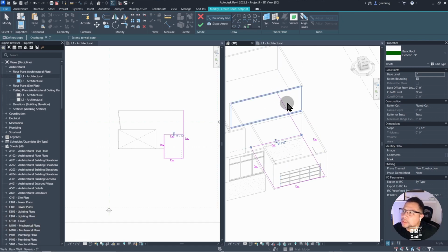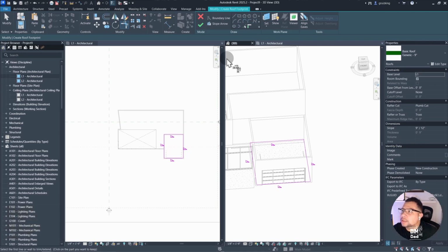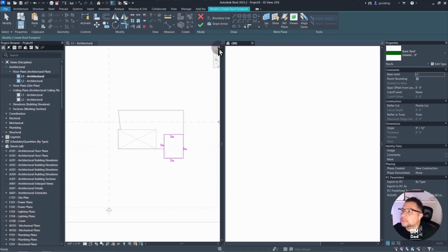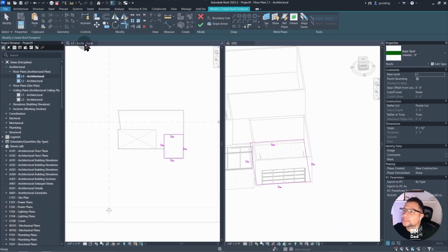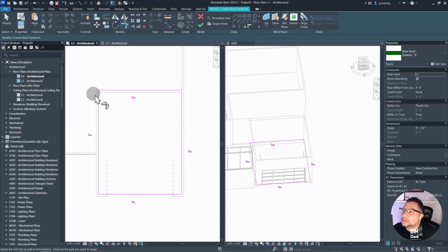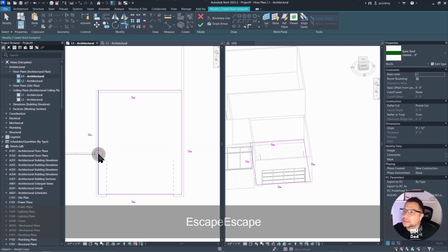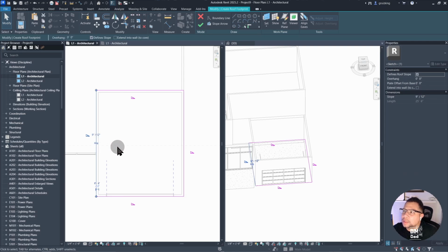Now, because of just typical modeling, I'm modeling this as one continuous wall. I'm not splitting it at two unless it's absolutely necessary. We're going to have to just trim here. Make sure that all your corners are trimmed. And just to double check, I'm going to bring over my plan here. So you can see I'm inside on one, outside on the others. I'm going to go ahead and flip that there.